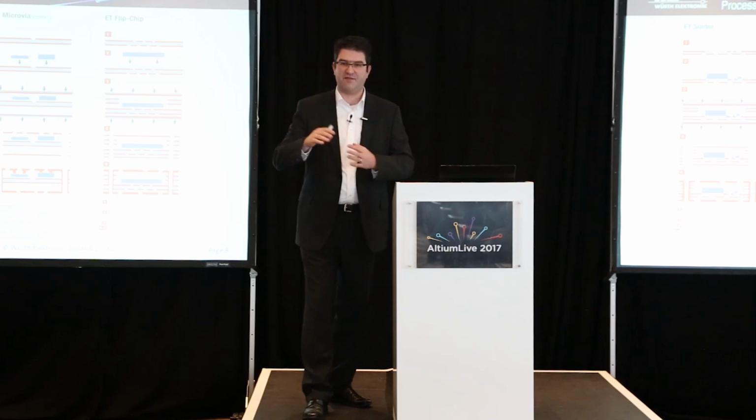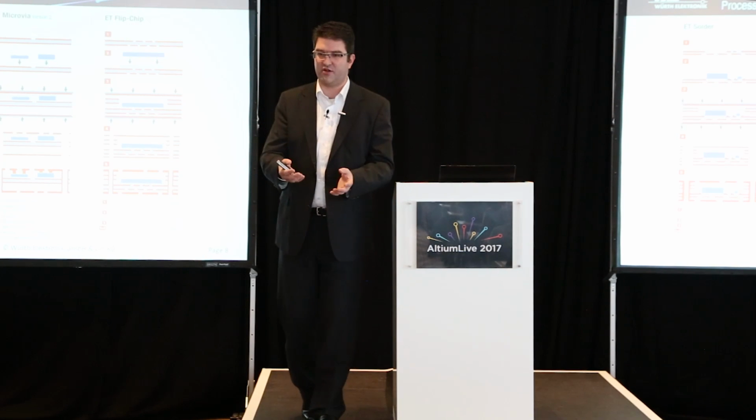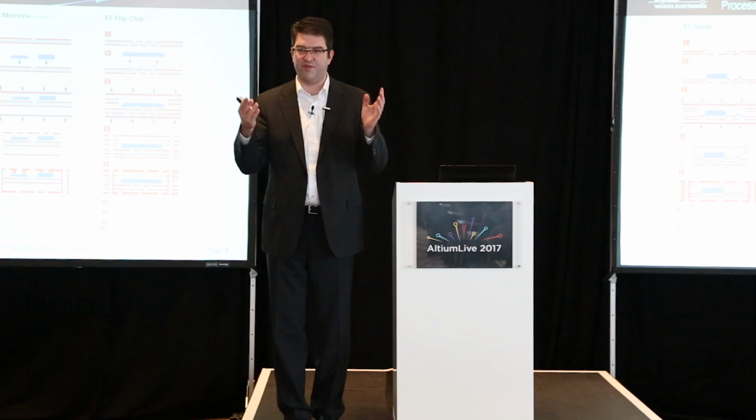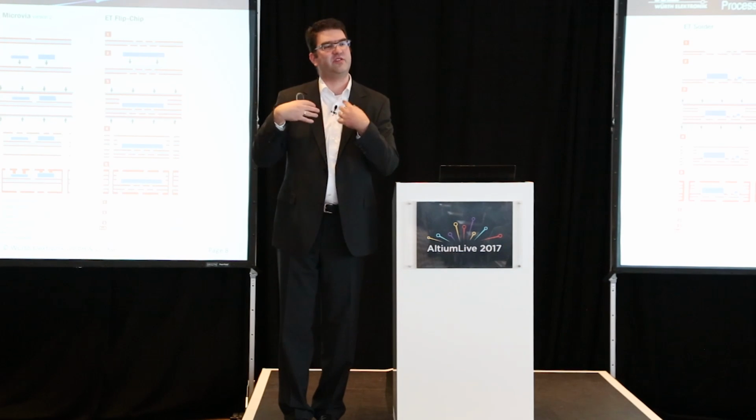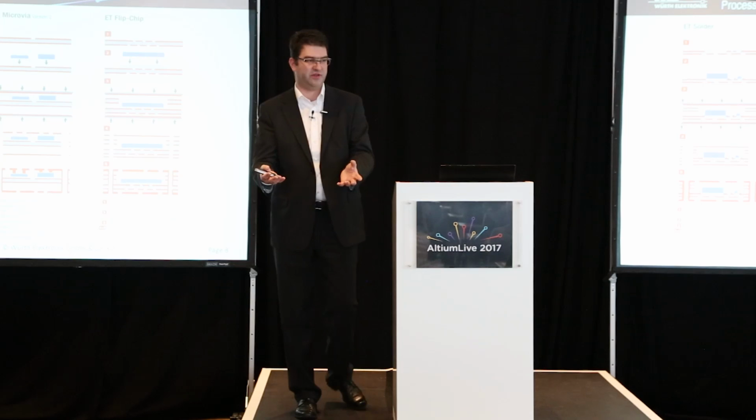Even when you want to test after lamination, the designer, the layouter, has to think about test points being visible on the top and bottom so that you can still access those components.